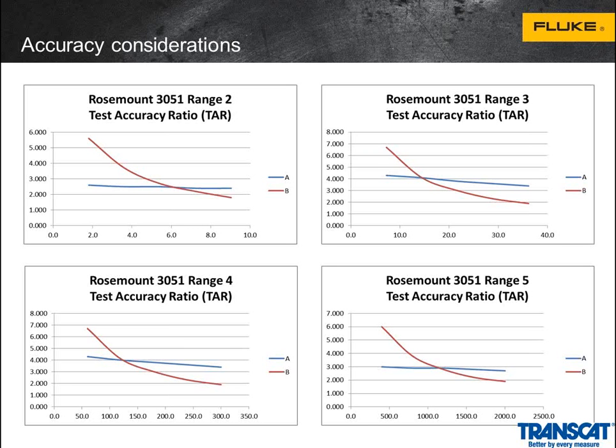And so one of the benefits of being specified as percent full scale is that when you get an out of tolerance, you have a fairly good idea of how likely it is that that calibration is actually the correct one. Whereas if you are using percent reading plus floor, you're actually going to need to calculate what the TUR was for that particular point and say, okay, where am I? How uncertain am I? If you're near the upper range, you know it's worse, but you'll notice that the graph is curved. It's not linear, so you can't just calculate 2 points and interpolate it. You've got to calculate the whole thing.